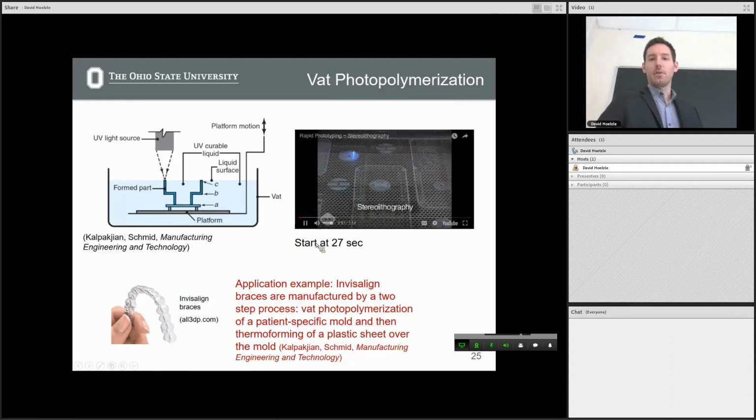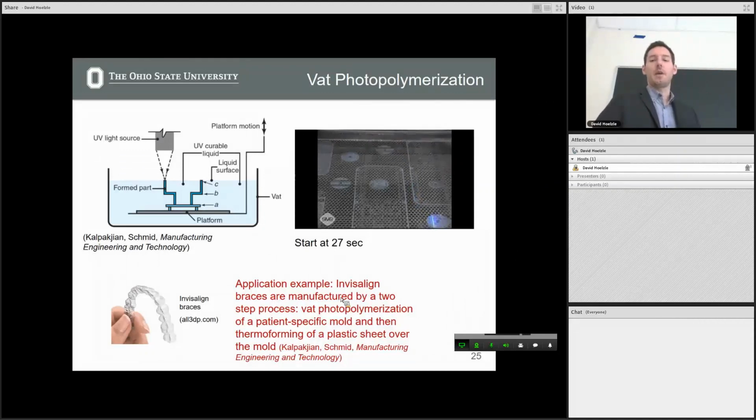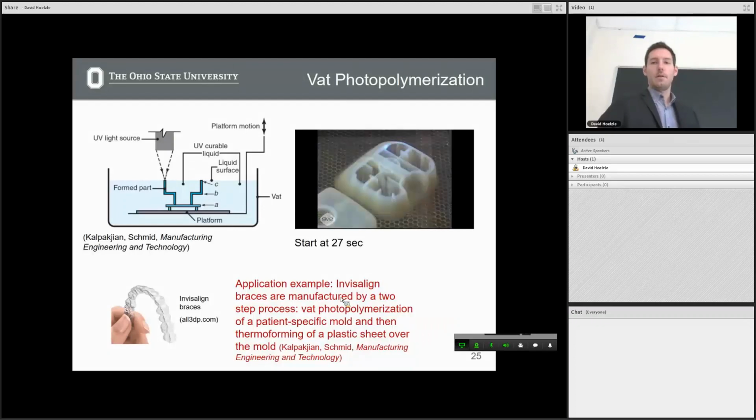So here is, you can see a laser exposure in the UV of this vat of material. It's mostly clear, so you can actually see the bed underneath this. You can see that kind of corrugated surface of this bed, but they're then exposing every layer. And here it is, multiple layers up, right? So everywhere around, it's tough to see because it's clear, is this photopolymer in this region. You can only see it when it becomes solidified.